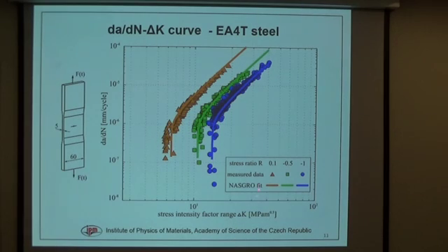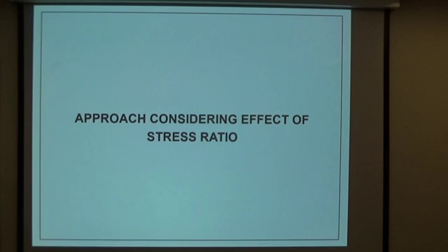Based on calculations, we measured crack propagation for the stress ratio -1, -0.5, and also for 0.1. This measurement was carried out on middle tension specimens, as you can see here. And now we should calculate, based on this data, the residual fatigue lifetime.